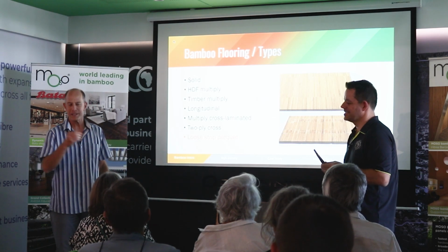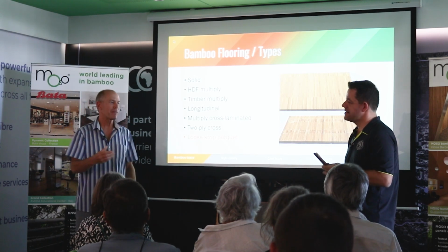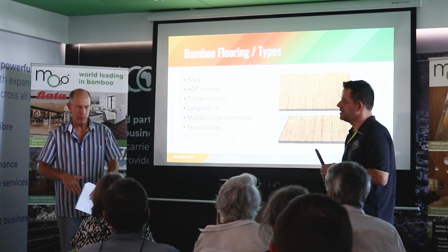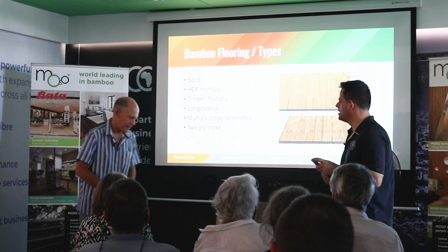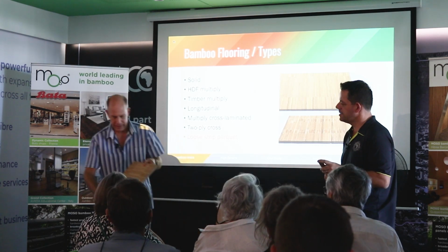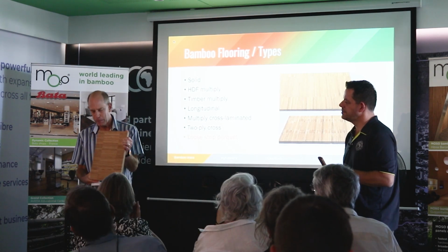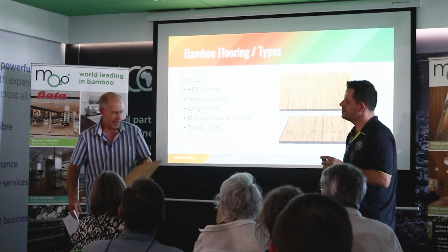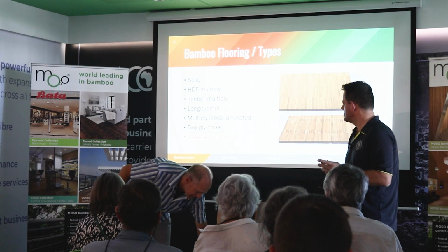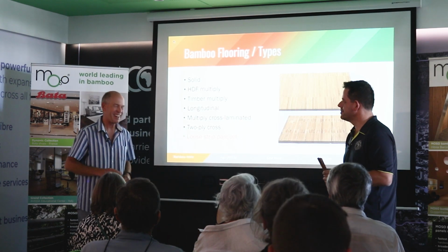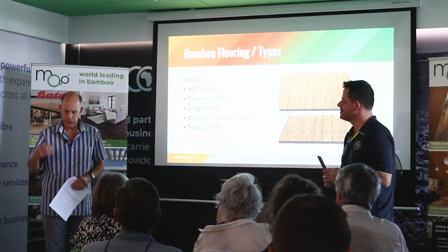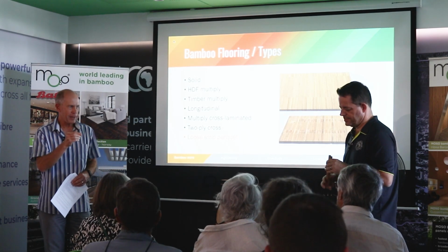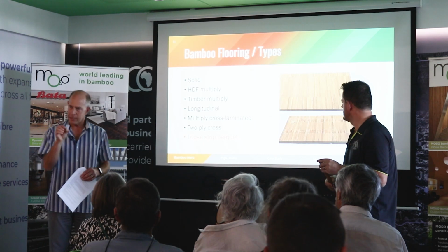The same principle as the old parquet timber floors, but this is all the strips are the same way. You can do it in a checkerboard pattern, but it gives almost a ladder pattern like that, which is very pleasing. The architects love it. And it's got some interesting technical features. So because it's tiny blocks, again, all the expansion and contraction is taken up within each block.